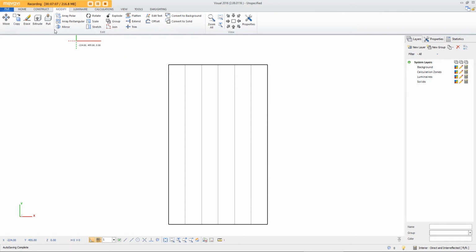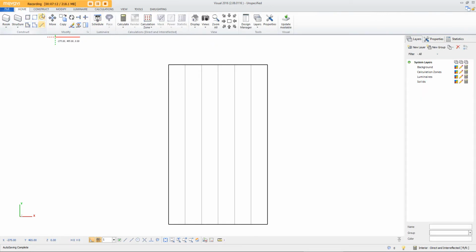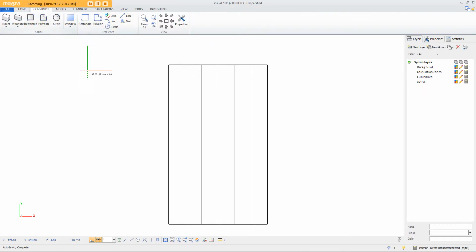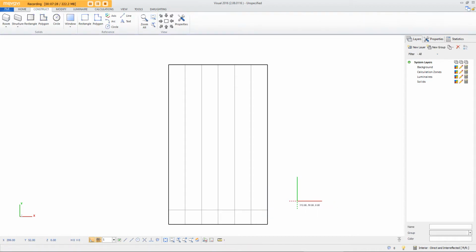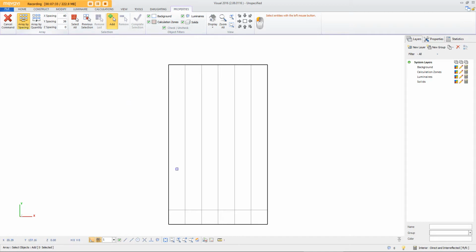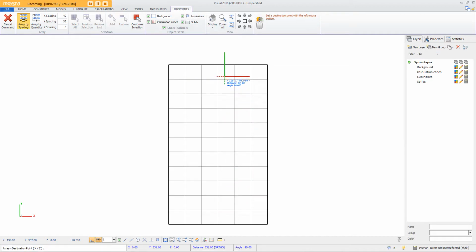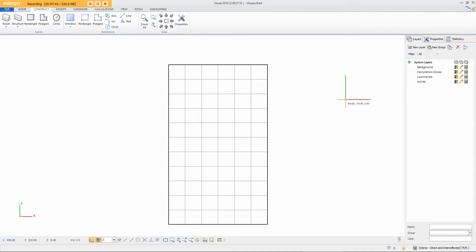So that's done. Next up we'll do another line, so you can press L, or you can go to construct or home. Home and construct both have lines, but again the hotkeys are the easiest way to do it. We're going to go up 36 feet, and it's a little bit difficult to get exact from further out, so you can zoom in if needed. We'll go right to the far wall there. The A for array function again. 36 is already inputted, and we will left click, right click, left click, and pull it up to the top. Okay, now we have our nice evenly spaced grid.